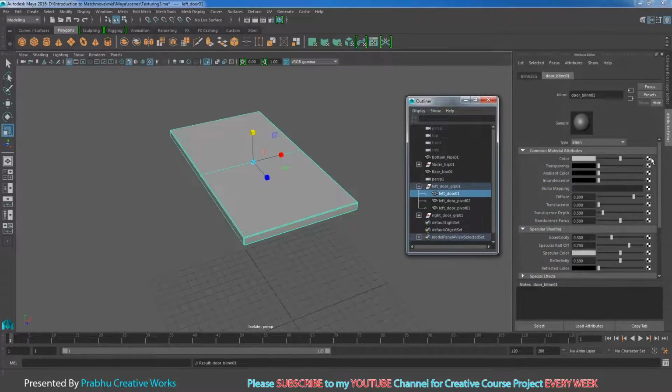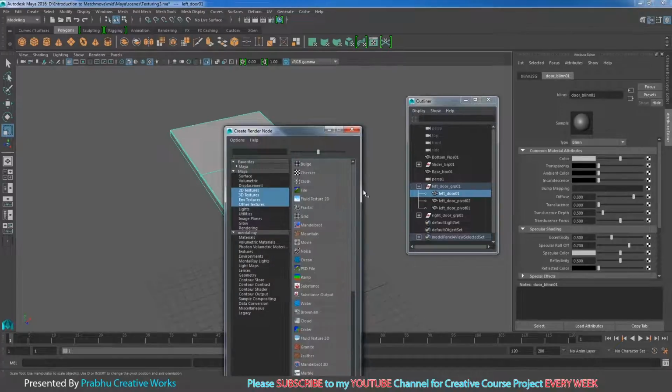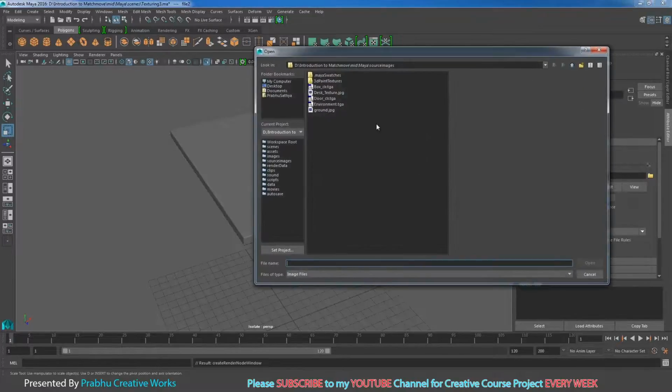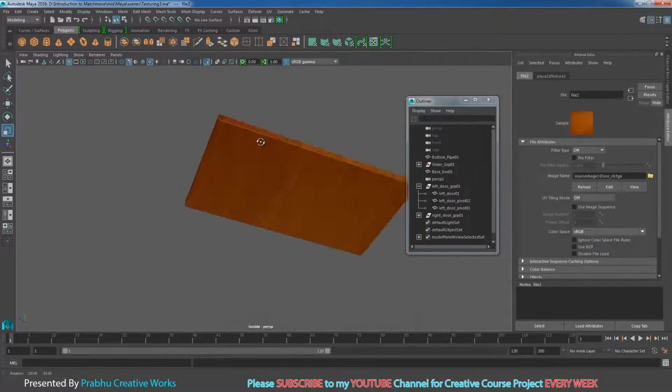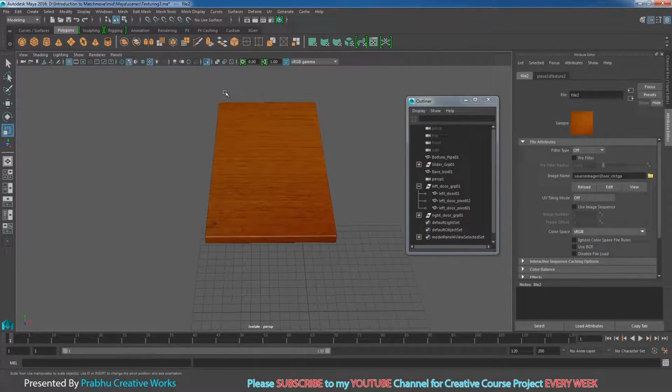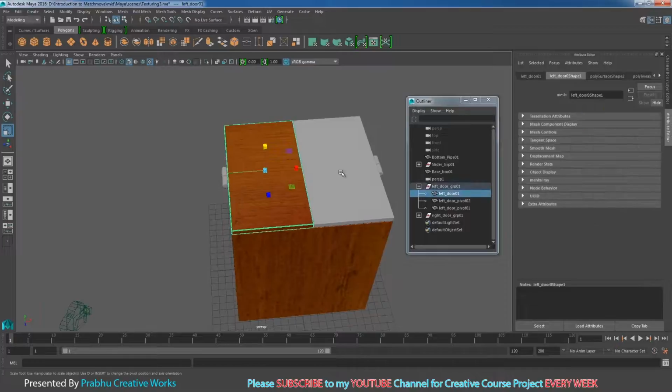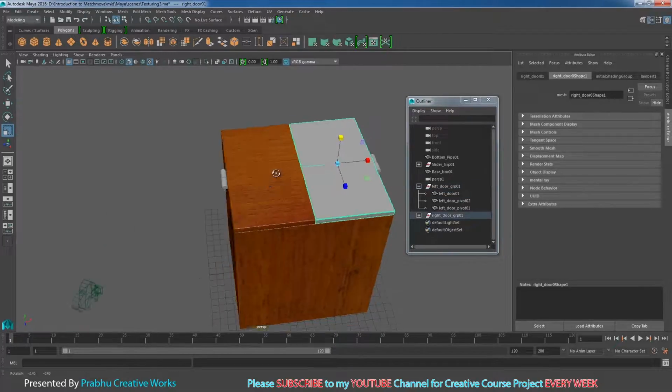So I will click on this checker box and choose file, and set filter type to off. Click on this folder and choose door_color.tga in your source images and click open. Now our door will be textured perfectly. I will re-isolate this object. Now I want to apply the same texture to this door also.